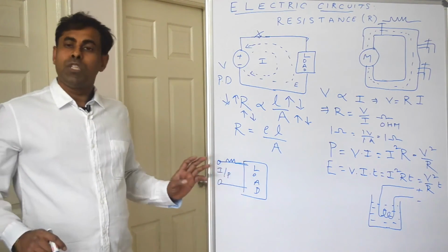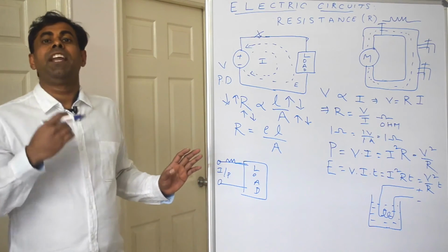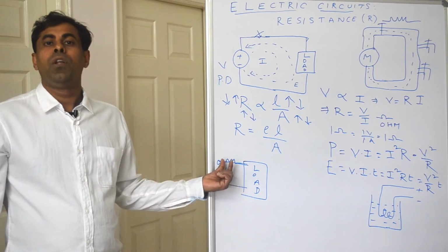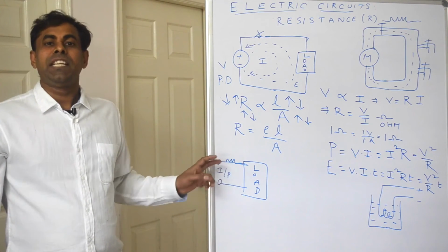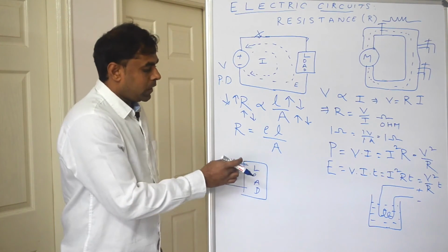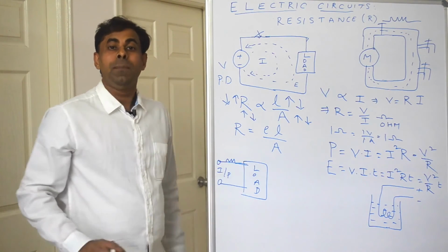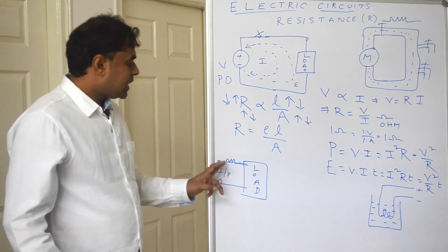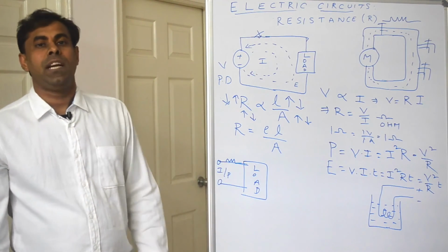Whenever we switch on the load, it takes a very high value of current. In order to limit the current, a small value of resistance is placed in series with the source. Whenever we switch on the load, this resistance is going to limit the starting current drawn by the load. This resistance is called an inrush current limiter.